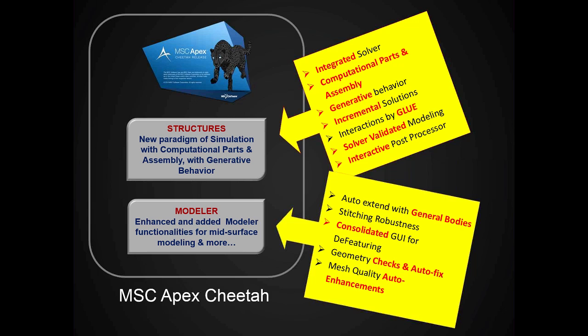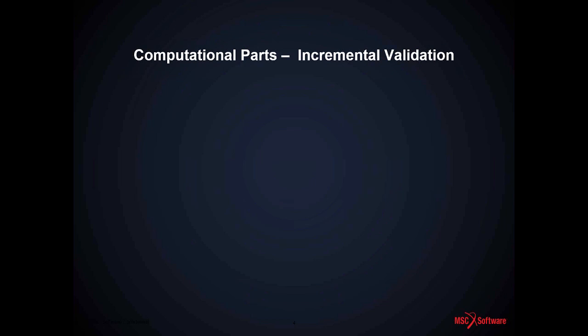We also give you a visual tool to find what errors are possibly in the model upon importing, and we also give you the auto fix. Most of these things will help downstream operations like direct modeling, edge and vertex drag, etc., because the model becomes clean. We also have what is called automatic mesh quality enhancement, which is included in this release.